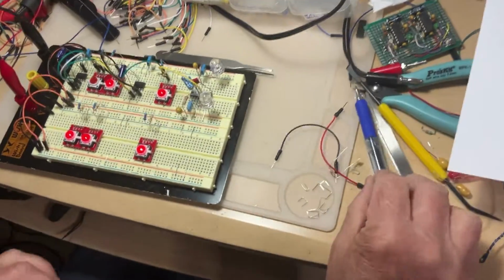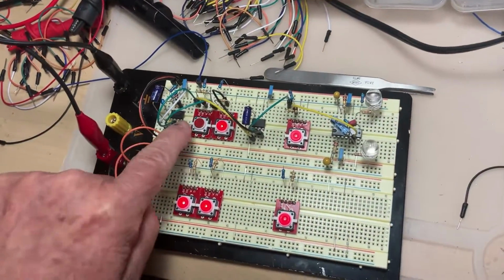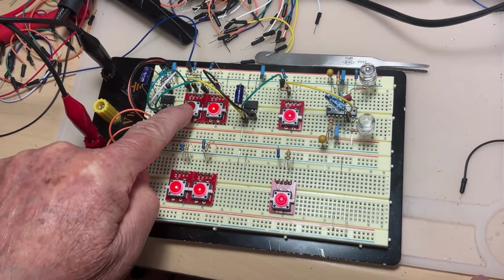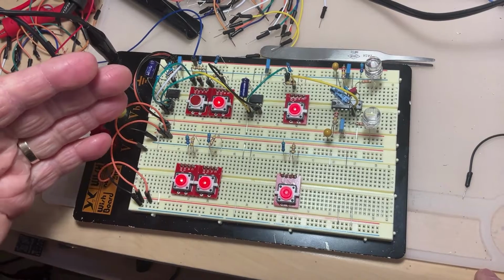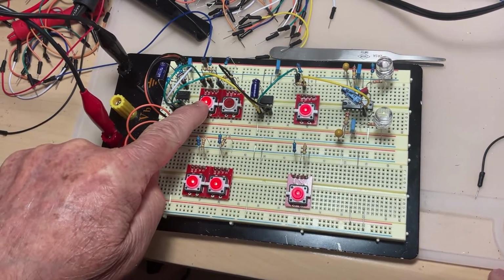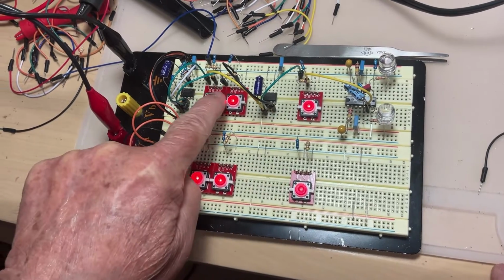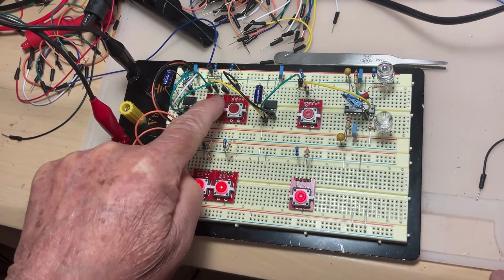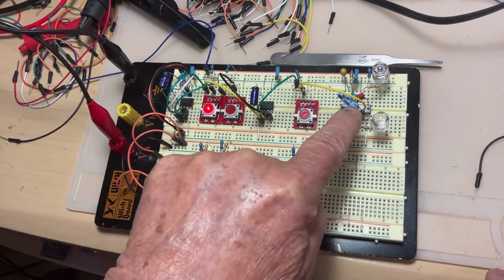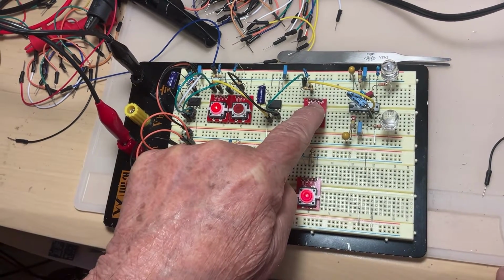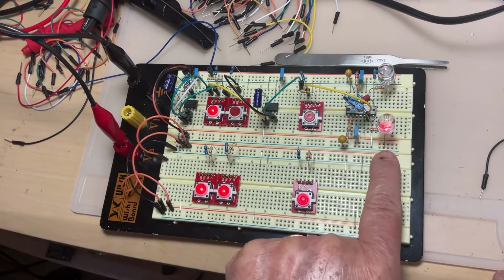So, very short summary again. This is the astable circuit. As long as the power is on, you won't stop. So astable is equivalent to not stable. So this is a kind of clock generator here. Next is the bistable circuit. On, off, on, off. And next is the monostable or the one shot. Because you press the button one time, it gives you one shot.